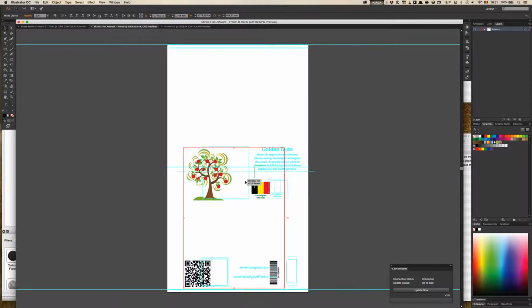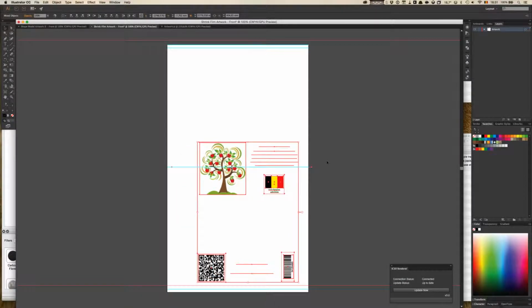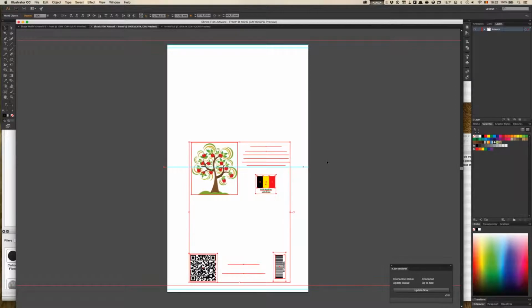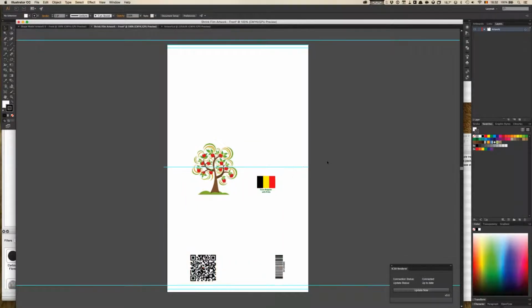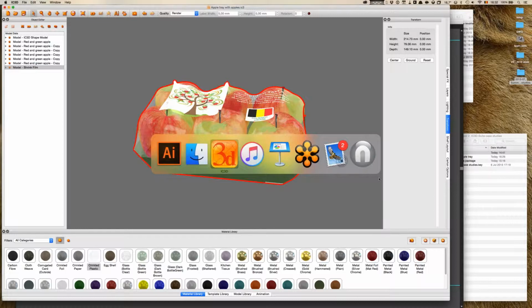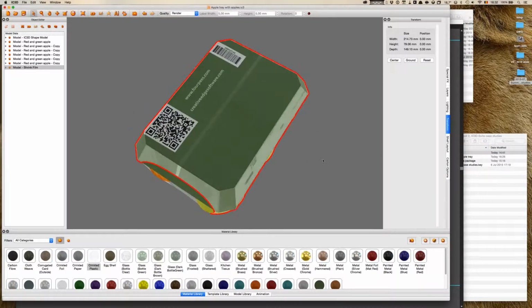And I want some rough positioning somewhere like there, but a little bit more in the center of the design, something like that. And now I can do update now. This is the plugin window, as you remember, that makes the link between Illustrator and iC3D Suite. So I'm updating that, and it shows that it has the artwork on here.